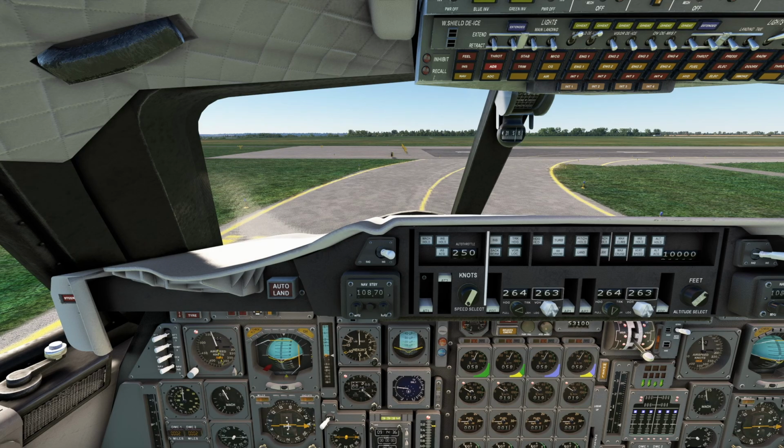We're at the holding point, runway 26 right. Quick departure briefing. On the runway, we're going to go to afterburners and full power afterburners for 30 seconds. Then we have to turn them off because of noise. 250 knots to 10,000 feet. Autopilot engage with INS mode, so we're going to follow the flight path. And altitude acquire to 10,000 feet.